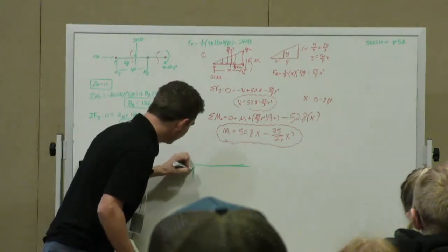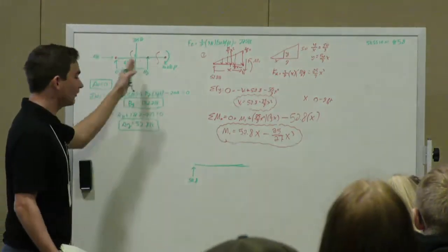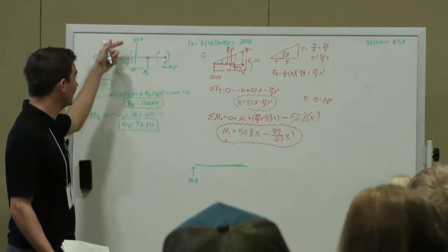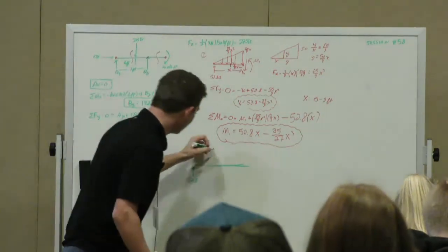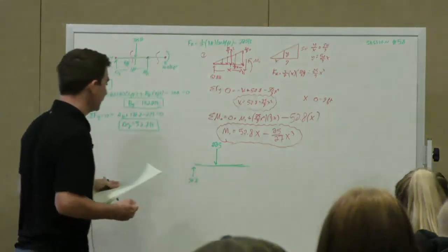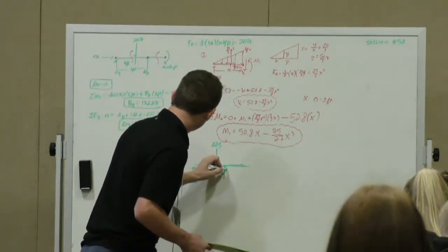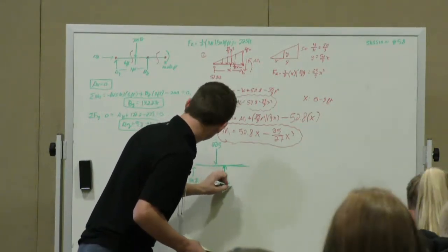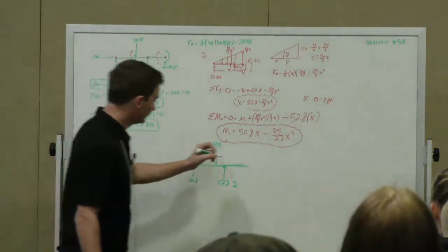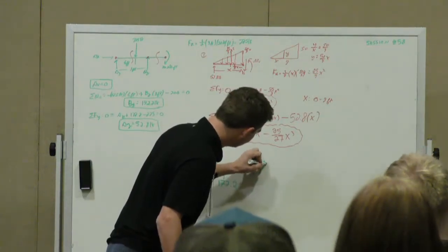Yeah, so now that our distributed load is before our cut, could we take the simplified version of it? Yes. So now that we have our full load, we can use the equivalent load of 225. What else needs to be included? Very good. What else? Yeah. So this will be V2. We're using the same convention, M2.